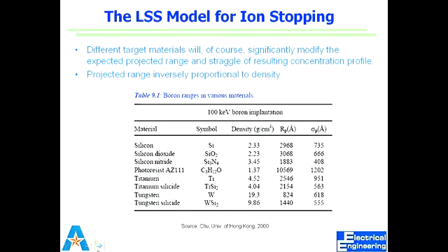Ideally, if I had my way, I would use silicon nitride because photoresist is crazy. It's like how much? 3 times that of silicon, right? But then, if you are a process engineer, what would you do? Would you want to clean your silicon wafer and do an oxidation run for, I don't know how long it's going to take to grow that much oxide, 40 nanometers, maybe it takes 5 hours, right? Or you just want to coat photoresist, which is going to take maybe half an hour, right?